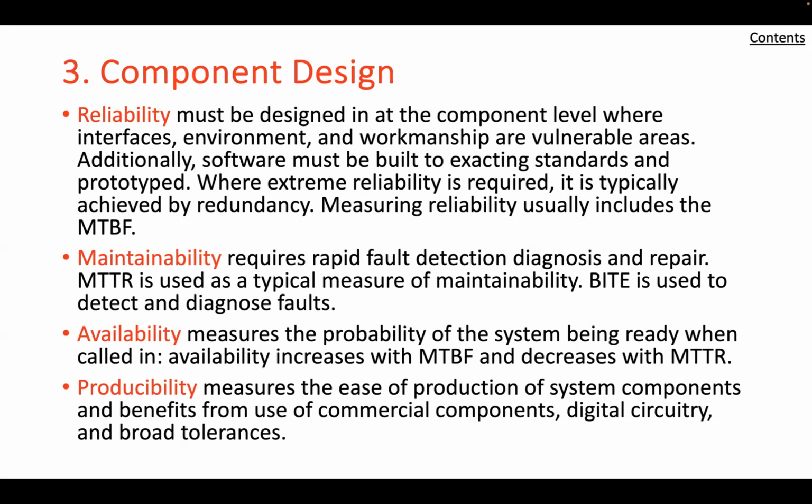A measure of system maintainability during operation is the mean time to repair, or MTTR. The time to repair is a sum of the time to detect and diagnose the fault, the time to secure any necessary replacement parts, and the time to effect the replacement or repair. The time to restore also includes the time to restore the system to full operation and confirm its operational readiness.